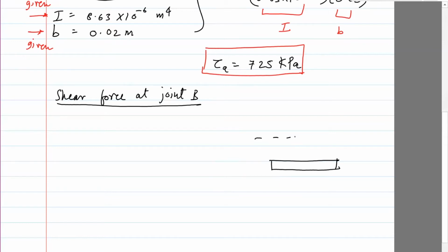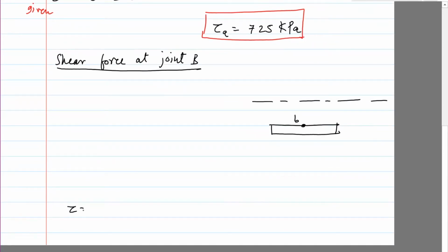So all you need to do is do the same math I did, except that you will look at joint B. So if you do everything right, you'll get shear stress of 608 kPa. Okay, so I'll fill the dots and post it, but I would like you to try it out yourself.